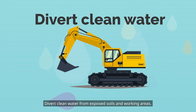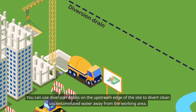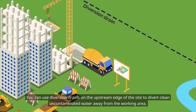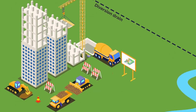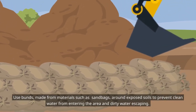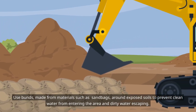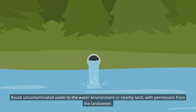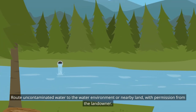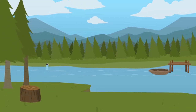Divert clean water from exposed soils and working areas. You can use diversion drains on the upstream edge of the site to divert clean, uncontaminated water away from the working area. Use bunds, made from materials such as sandbags, around exposed soils to prevent clean water from entering the area and dirty water escaping. Route uncontaminated water to the water environment or nearby land, with permission from the landowner.